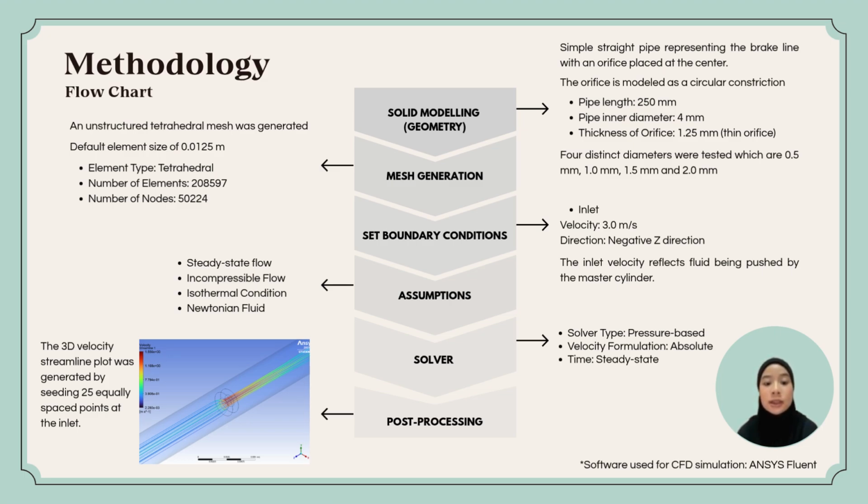This inlet velocity reflects that fluid is being pushed by the master cylinder and the direction is in the negative Z direction. 4 assumptions were made for this CFD simulation, which is that we assume the flow to be steady, incompressible, isothermal, and the fluid is Newtonian. Next, our solver type is pressure-based with absolute velocity formulation and steady state. And lastly, for post-processing, a 3D velocity streamline plot was generated by seeding 25 equally spaced points at the inlet.